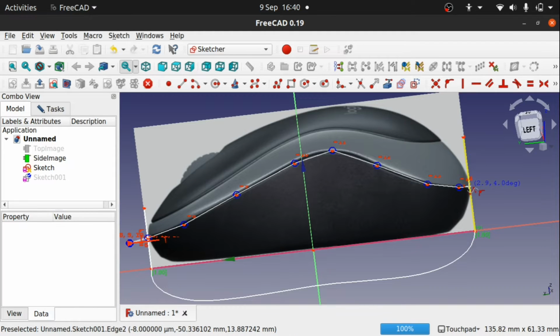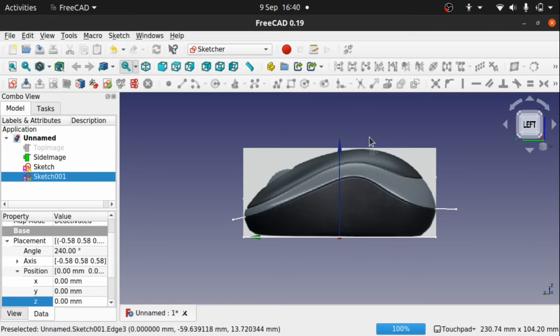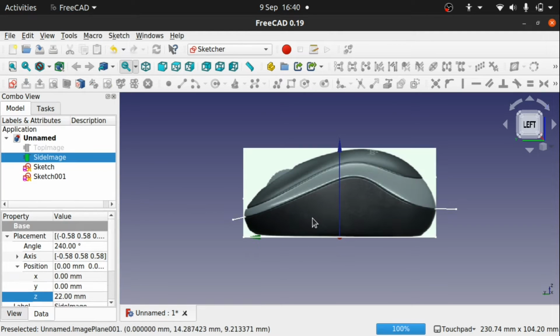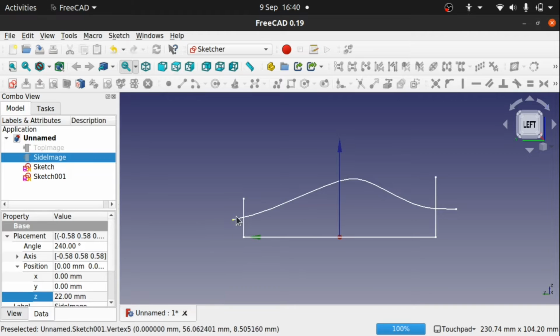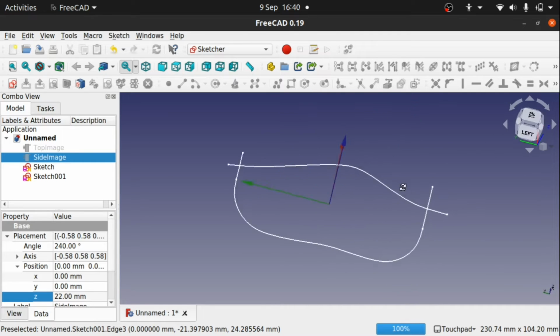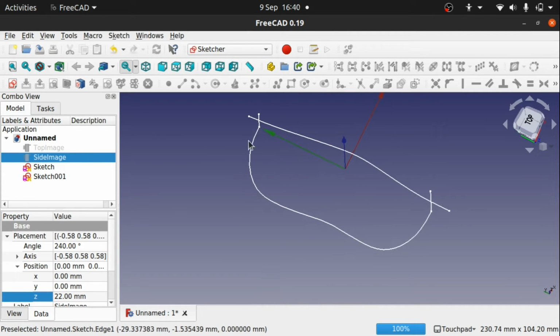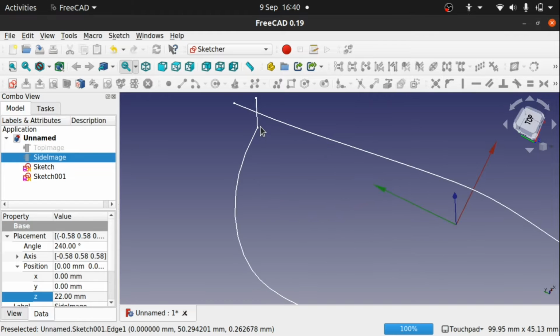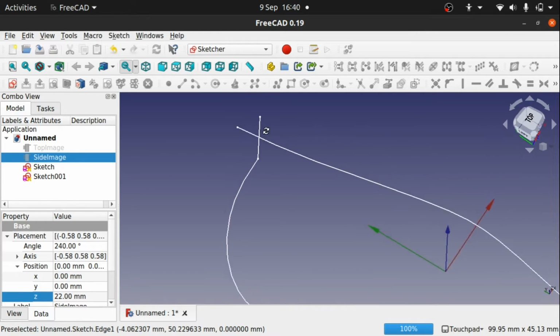And when we get to here, we're going to connect up to that line again and then click further on and hit escape. Hit escape again, and that'll come out of the sketch. So at the moment, if we look, we've got this line that crosses these two horizontal lines. That's important when we create the mixed curve, because if we look at this, you can see that horizontal line there connects up with it,